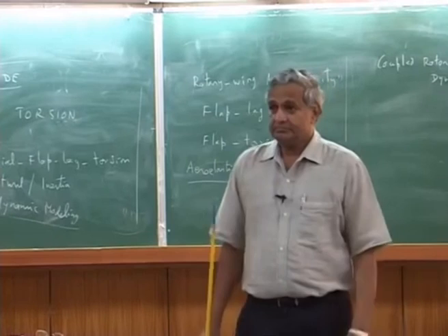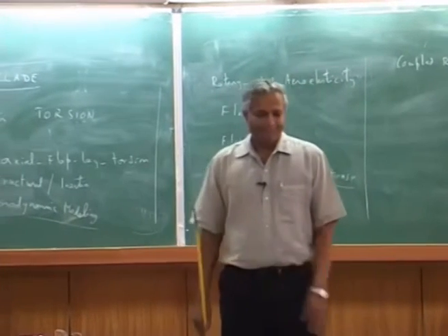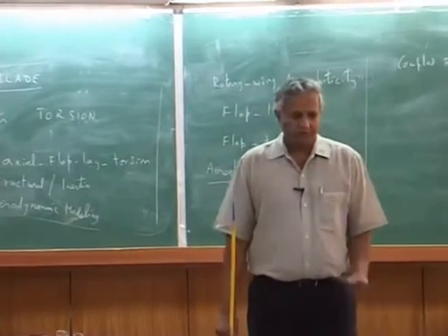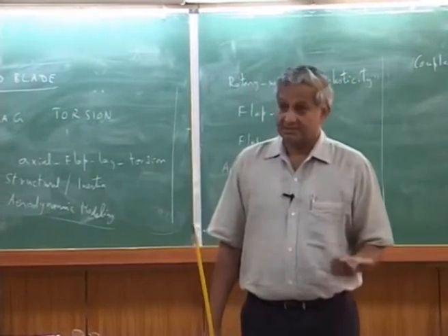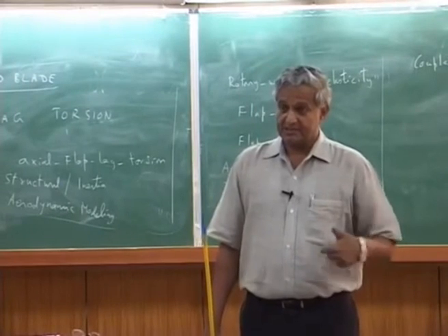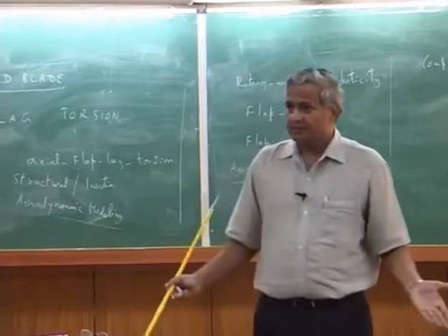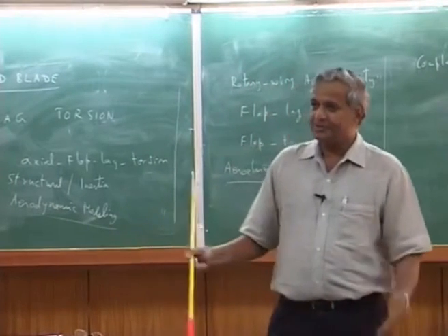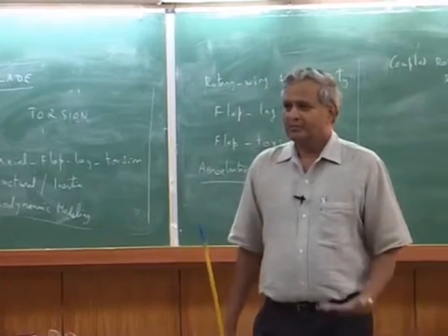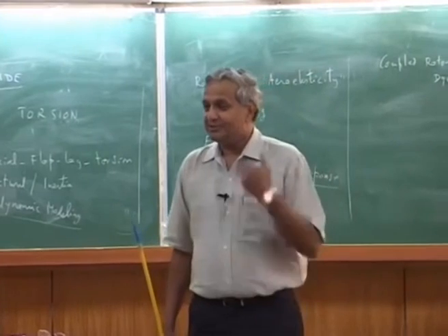So the spring which we are modeling for flap, the spring constant would be far lower than the... Spring constant, you try to estimate. Estimate the spring constant from frequency. That's all. And the hinge offset. If I measure that spring constant with respect to, say, blades, what is the question of measurement of spring constant? There is no measurement. You measure only the frequency.